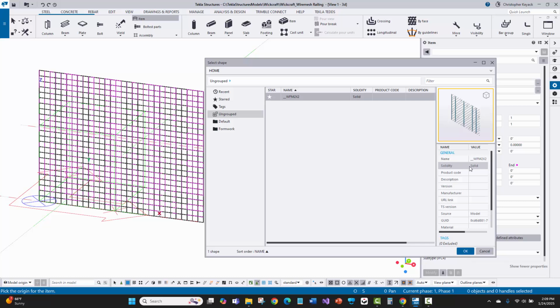If you did an IFC export of this and then told it to import the shape directly from a created file like an IFC or a STEP file or something that you exported from Tekla or even SketchUp, the thing you have to watch out for is sometimes when you import things from other files versus natively converting them from within Tekla, it doesn't create a solid, true boundary representation around the entire object. And if it doesn't say solid, then the weight will not be calculated properly because the volume can't be calculated. So that's something important to watch out for.